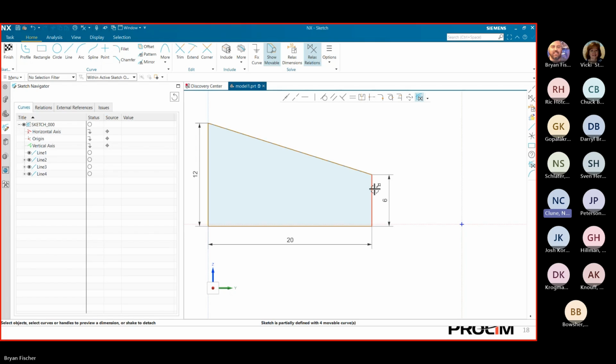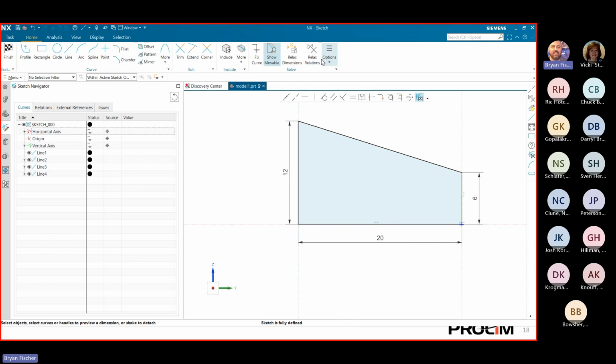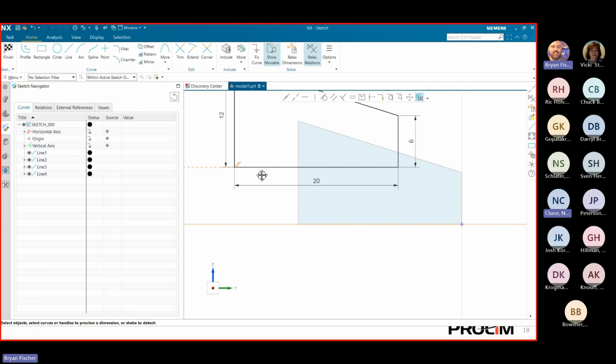Okay, that's exactly what I was looking for. So when you put that initial constraint, I guess we'll call it a constraint, it's collinear I put here. And if that was turned off, you can't override it, I guess. Exactly. And then I have the collinear here that I could put in. Now, if I have relaxed relationships off, I can't move it. As soon as I turn the relax on, it's going to let me go in there and relax that.